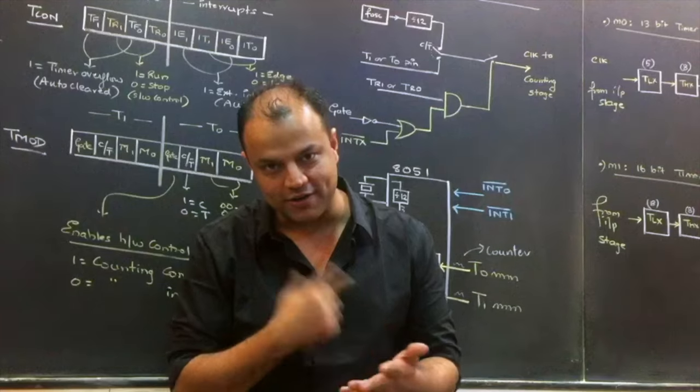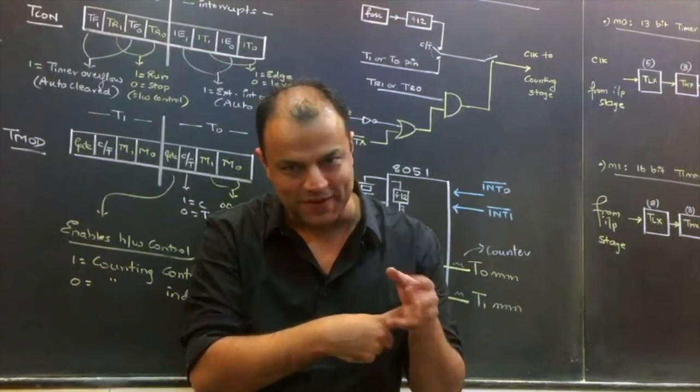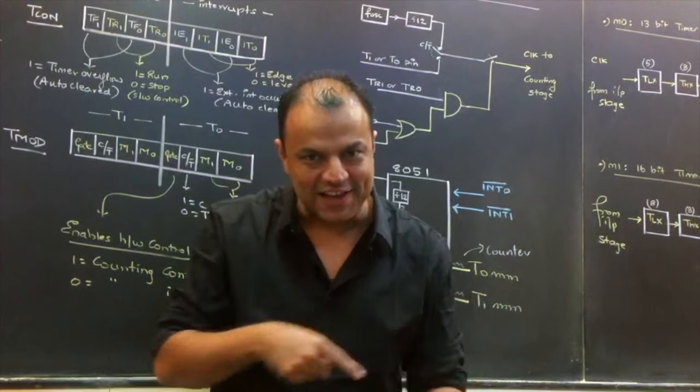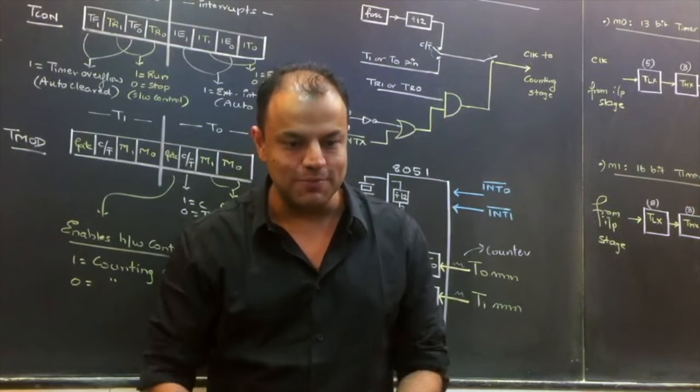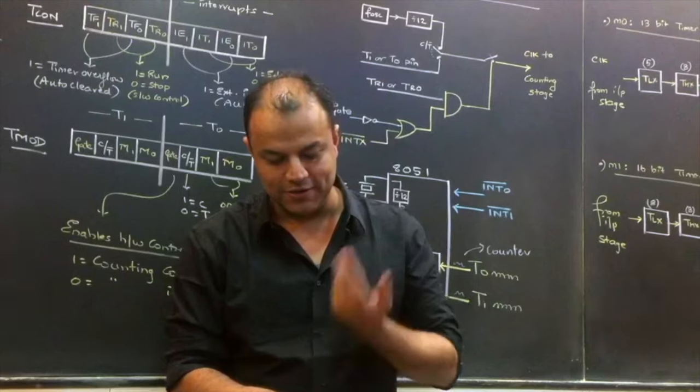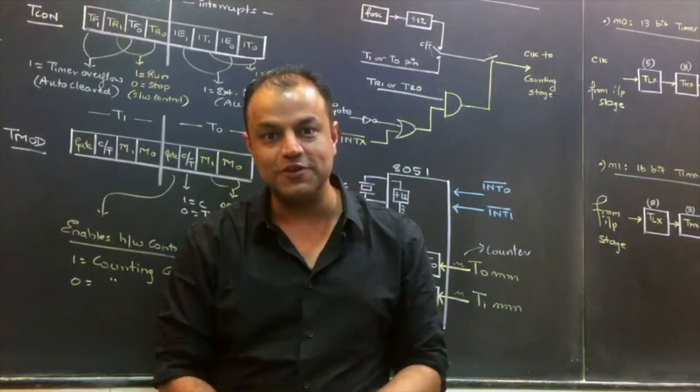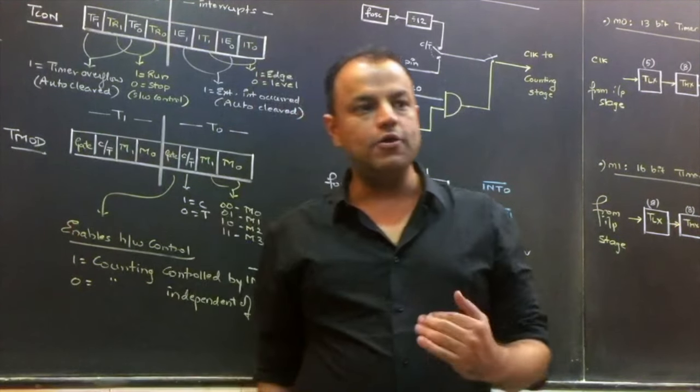That means it is what triggered? Edge triggered. It's not interested in the press position. It's interested in the pressing action. Tell me, did you understand this? On the other hand, if you think of a computer's keyboard, you hit M, M comes on the screen. Don't release your finger. M will keep coming on the screen. It is level triggered. Anyway, I hope you understood my point.